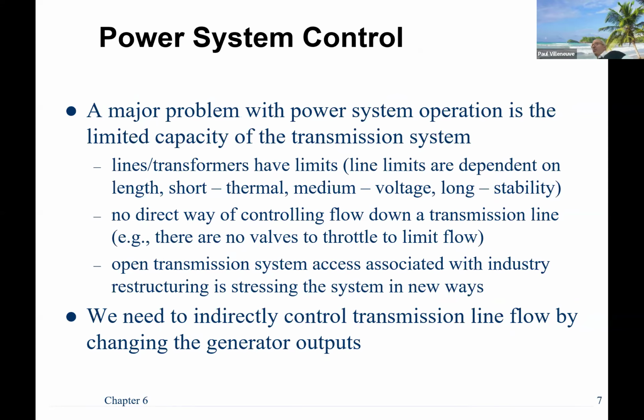So once you've set up your system with contingency analysis, now we have to make sure, do I overload any pieces of equipment? I calculated 700 amps. Is that a problem? Well, it depends on the line rating. And the line rating actually has 2 ratings. Actually, it has more than that. But the ones that we worry about are winter ratings and summer ratings. Kind of makes sense, right? In Maine in the winter, it's a heck of a lot colder than it is in the summer. So you can run lines at more power in the winter than you do in the summer. It may not necessarily be exactly the case if you're in Florida, where the temperatures are a little bit cooler in winter, but you might not get as much margin.